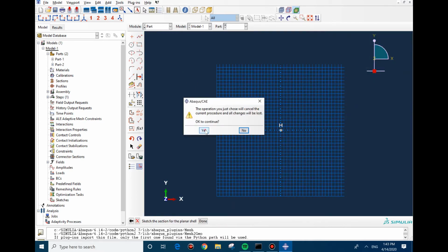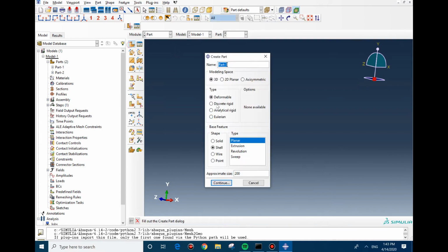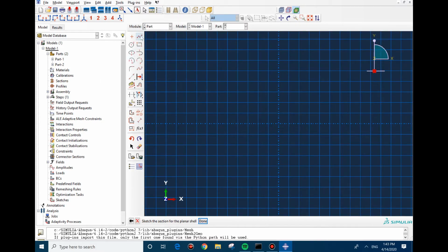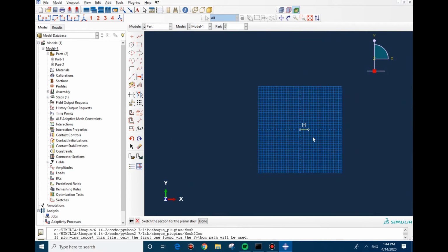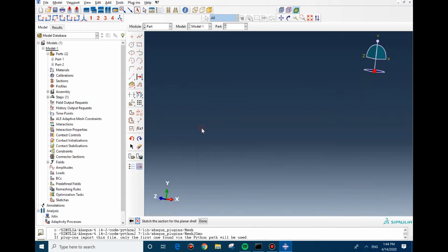Okay, I'm going to go out of it, but when I click on it and then I put 10, for example, and then I put the same values, 0 for center and 1 in x, 0 in y direction, you can see it's bigger than that one. So it's kind of acting like a lens in a microscope. So by changing the value, you can scale your model. Okay, and I just wanted to define that.